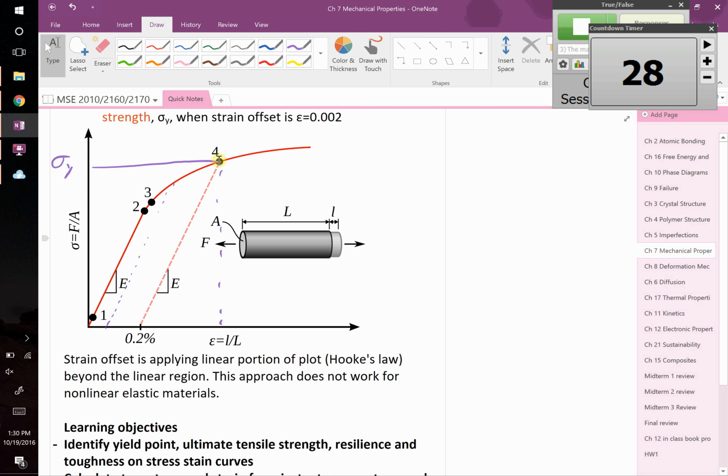We called it plastic deformation that's not there instantaneously, but over time it is there. We called that creep. So you're talking about creep. So to solve this, these plots don't take into account creep. You'd have to have a more sophisticated stress versus strain plot to account for creep, right?